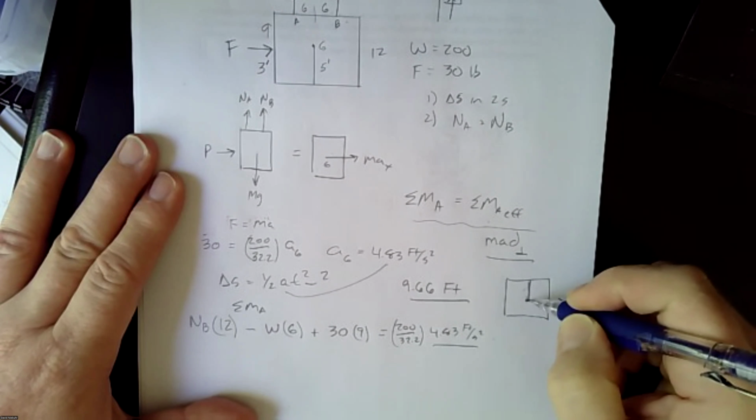So, for example, we're going to sum the moments about B. The reason we're going to sum the moments about B is because that's going to get rid of the normal force B and the friction force mu static NB, since we don't know those. So we take the moment about B, that eliminates them. Now, we're assuming that NA is 0, which means that we want to know what is the maximum friction so that we can cause it to just start to wheelie, but not wheelie.